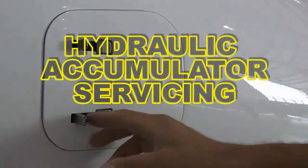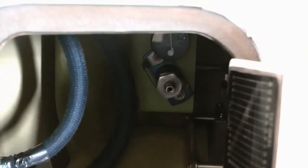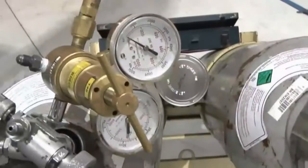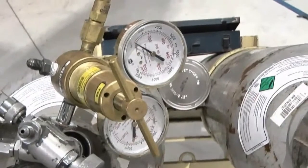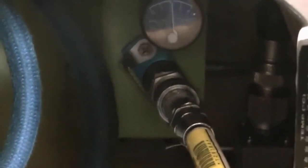Hydraulic accumulator servicing. Remove the cap from the charging valve. Install a high-pressure servicing regulator on the nitrogen cylinder. Connect the hose to the charging valve. Open the cylinder valve and, with the pressure regulator valve, adjust the pressure as given in the chart. Stop the nitrogen supply when you get the pressure shown in the pressure gauge.